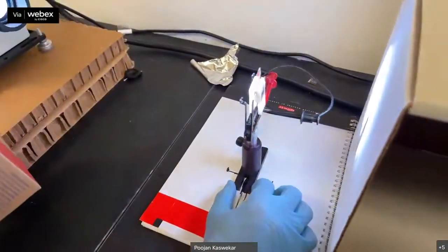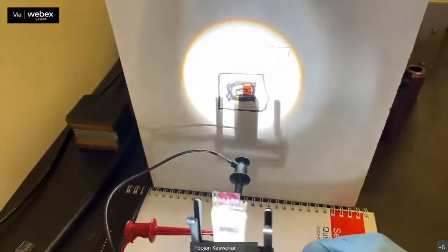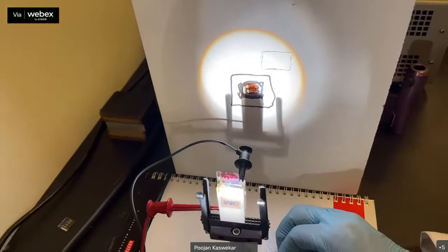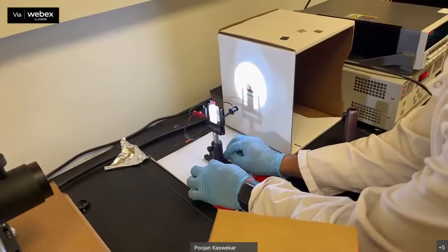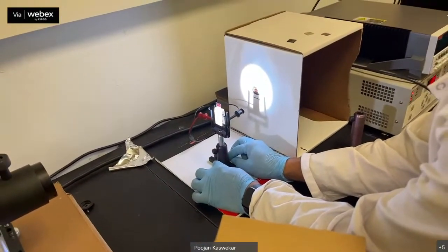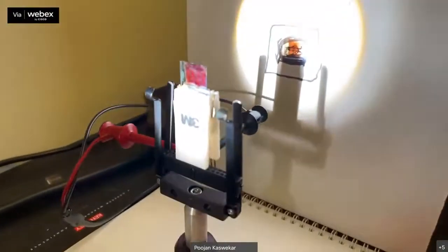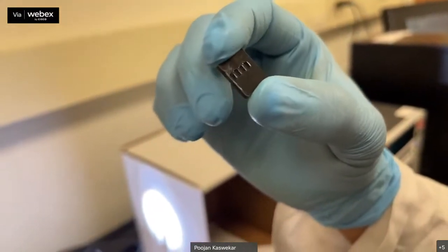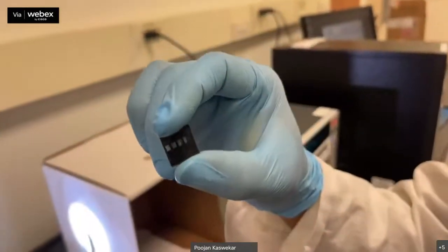So I'll see if the height is matching. You can see we marked a circle over there, so we'll match the height of the solar cell and the distance between the lamp and the solar cell as well. Typically this is called light soaking, because some solar cells work better with light soaking and some work better at lower temperatures. So we'll continuously blow air on top of it. And if you can see, this is the 0.04 centimeter square mask we designed to measure the smaller area. The usual one is typically 0.09 centimeter square, and this one is 0.04 centimeter square.